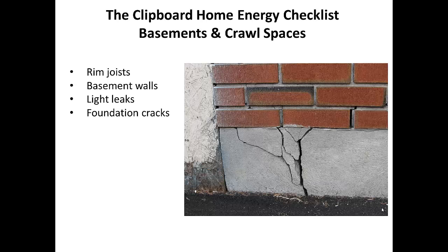Another thing to look at are cracks in the foundation. A lot of times these cracks will go all the way through. Sometimes they need to get a professional to take a look at it. But if that crack goes all the way through, that's a ready-made place for air infiltration to come through, let alone water or other things. So those certainly need to be addressed.